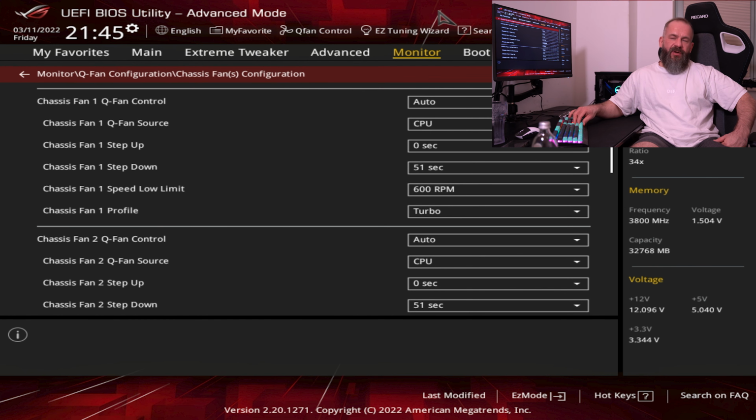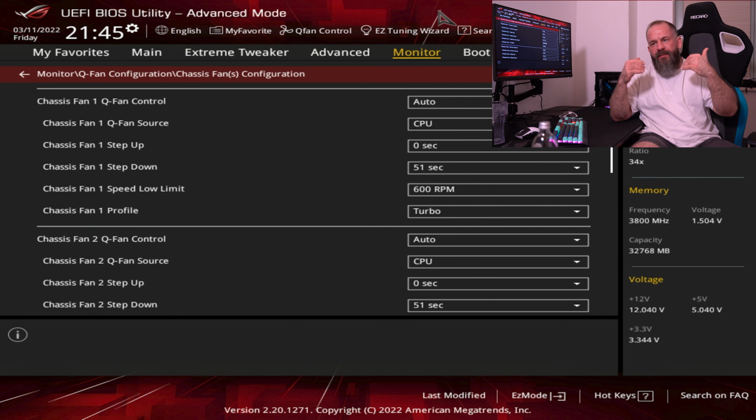Please don't go too conservative or too low with those rates, or in general with the cooling. If you don't have a super nice cooling system, very good high quality radiator, fans, whatever, just keep it a little bit higher. Just keep it minimum 50-60%. Why? You just want to have it already running at a stable temperature. The whole system should run at a good stable temperature, which is not that high. I try to avoid 60 degrees on the system in general. I try to avoid 60 on the CPU and on the GPU, and it works. I can tell you this feels very good, because thermal throttling of frequencies is very common, and it sets in very early, not when it's 80 or something. It starts at a way earlier point.